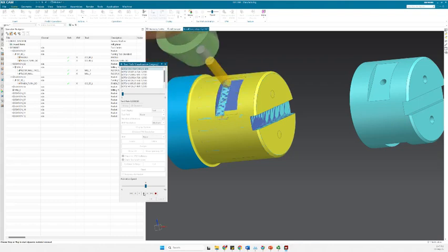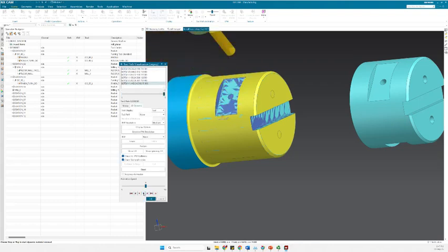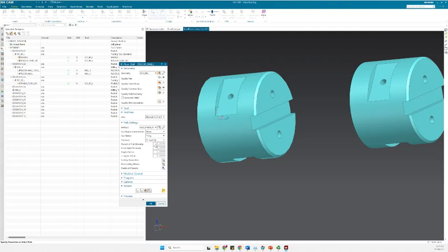So the more you put, perhaps you are getting better surface quality, but not necessarily, because it's increasing the machining time anyway. So I think 75 would be a good number, but you can also check this one with the final quality that you get. If you machine something and you see that there is some material left, you can change these step over values also.